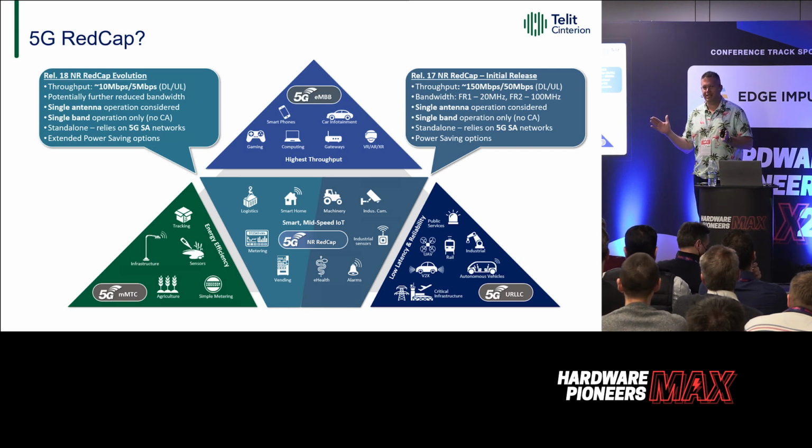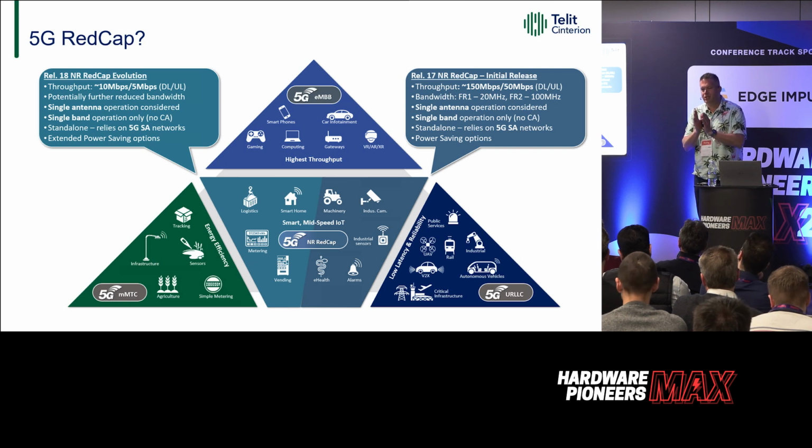Cat-M and Narrowband IoT are intended to continue through the 5G era. What we're seeing from the network operators, especially in the USA, is that even when they move to a 5G standalone implementation, they're going to maintain a sliver of spectrum, either band 12, band 13, whichever network operator you're using, so Verizon or AT&T. A sliver of spectrum with a 4G radio, RAN tower, connected to a 5G core, which is able to host Cat-M and narrowband devices still.